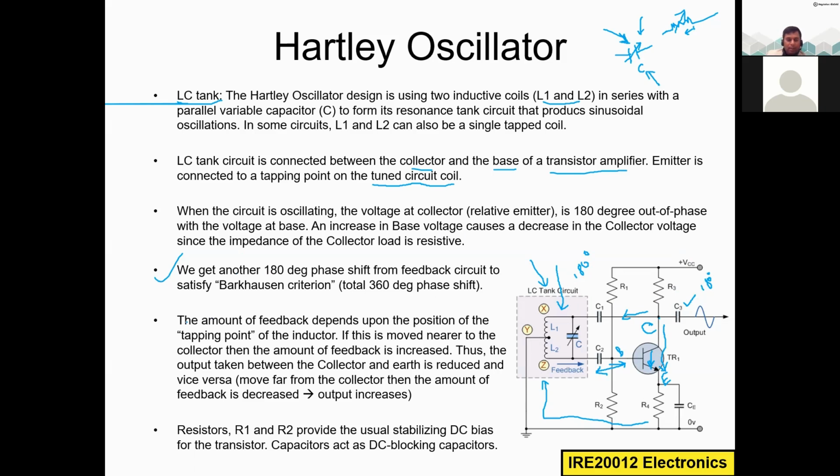This is okay. So the amount of feedback, so we are taking this feedback here, really depends upon the position of the tapping point of the inductor. Here you can see the tapping point. If this is moved nearer to the collector, then the amount of feedback is increased.